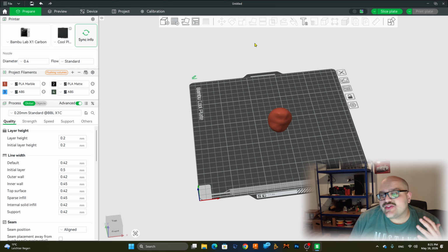And the layer height is almost always going to be a multiple of your total object's height. And the layer height has a minimal and maximum value. You can press it at 40% of your nozzle diameter as a minimum, but you're not going to be able to go under it while also having guaranteed quality. So your layer height really is part your decision, but it's also constrained by your equipment.